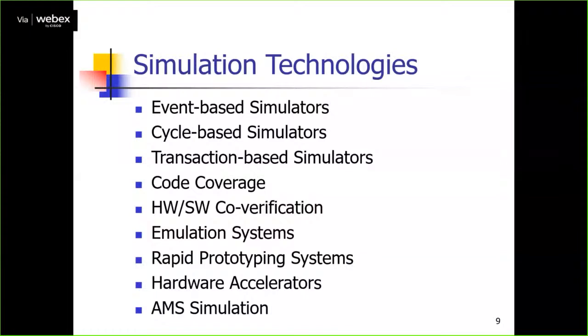The changing of the appearance of input A and input B at times t1 and t2 is called event occurrences. In these types of simulations, you change your input appearances at every time period and check that the functionality is verifiable. Such simulators are called event-based simulators.